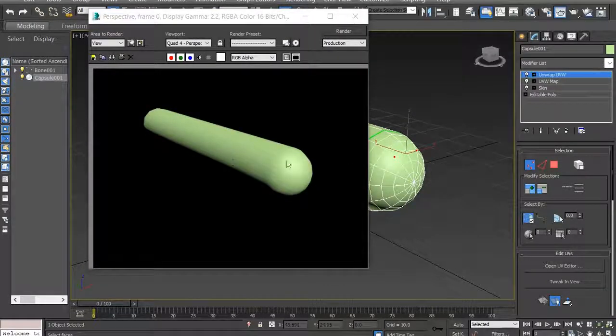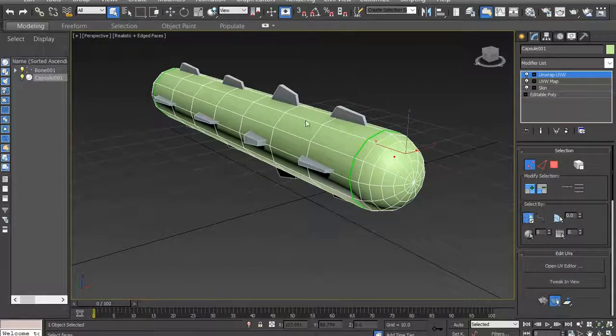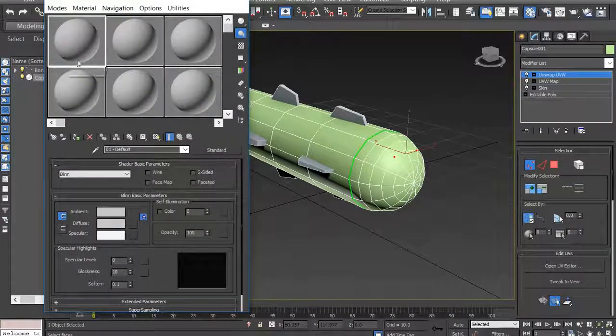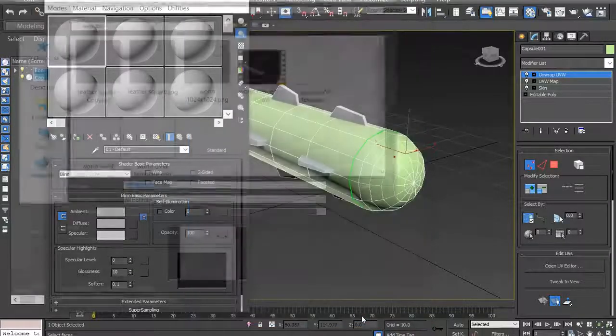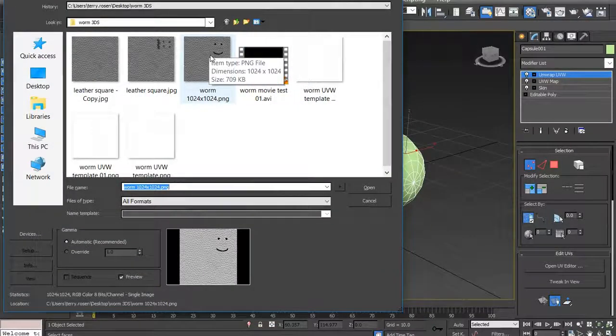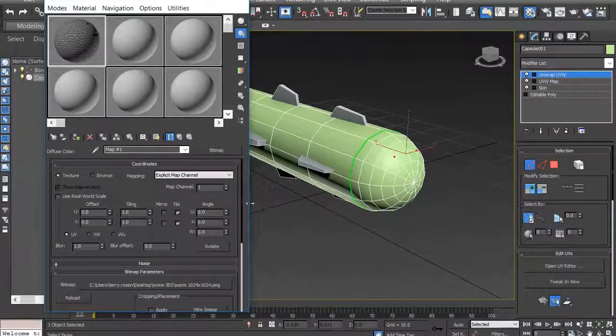So you see it's still green, even though we've mapped the texture to this map. We don't have an associated texture over here yet. So now we need to make that texture. So to do that, we're going to go to the material editor. We're in a square. This is fine. Our default is fine. So we go down to diffuse, click this. Again, go to bitmap, hit OK. Select the same bitmap. I just double click to load it automatically.